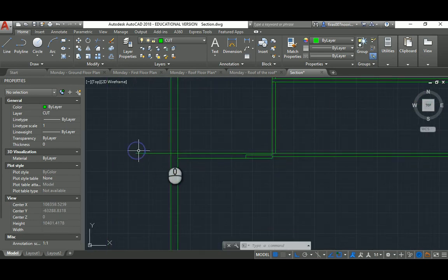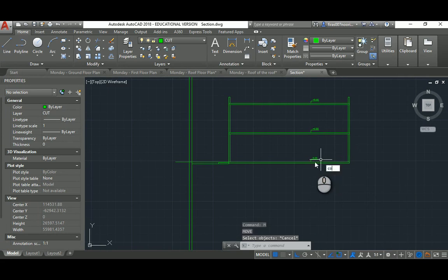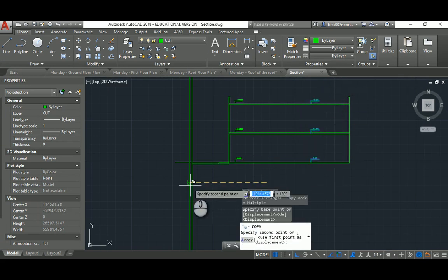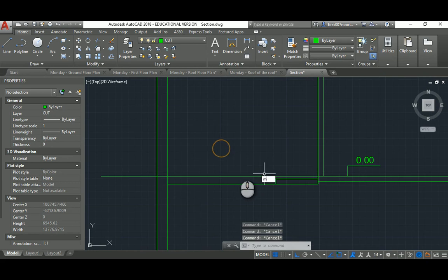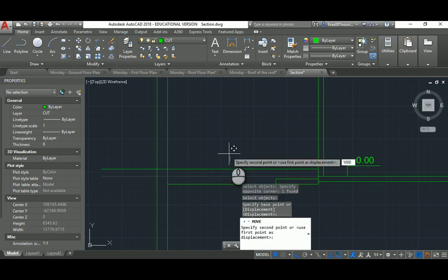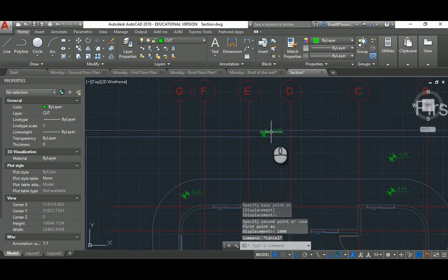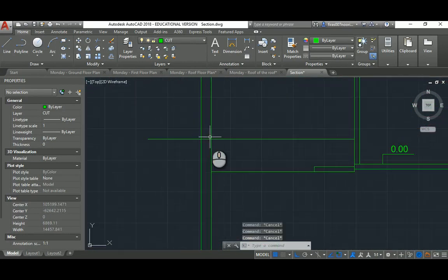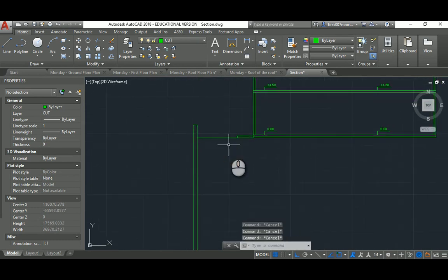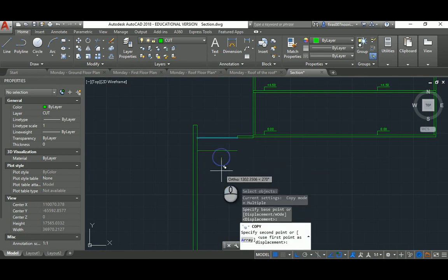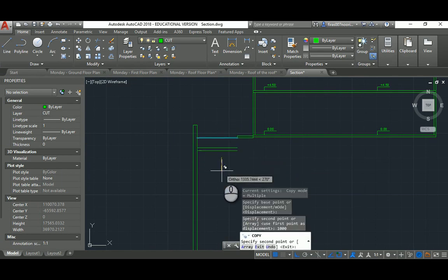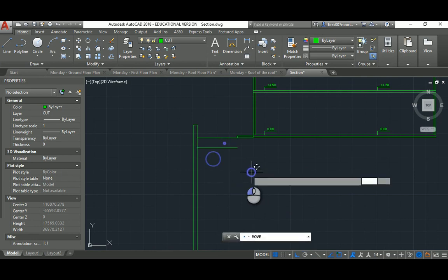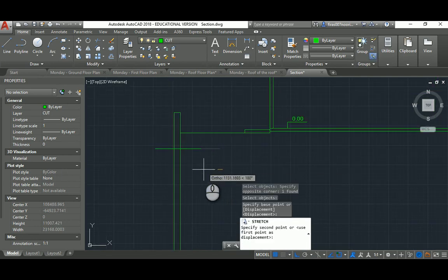And the fence is just 1,000. So I'm going to take from the 0, 0 again. Always keep the scale with you. So that's the 0, 0. Push it 1,000 up, because the fence is specified as 1,000 from the level of floor finish. And I can copy those lines down. Let's say another 1,000, and I'm just going to move that as such, and just got it.